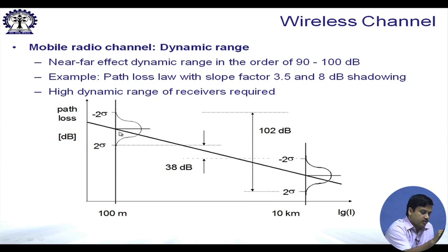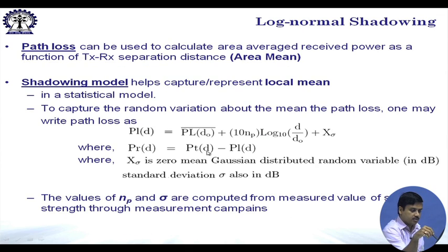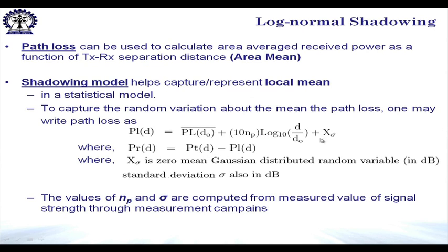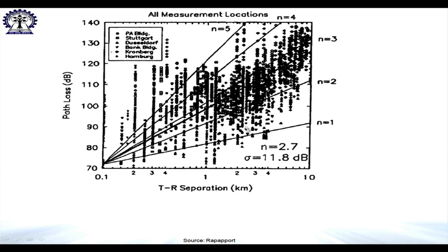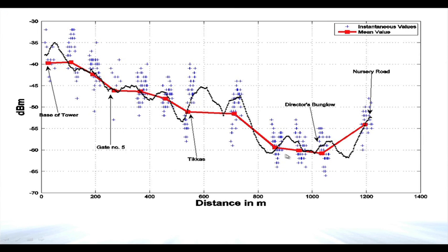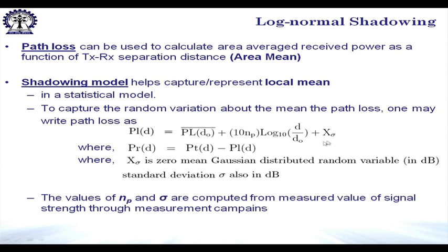That means, when you are close to the base station, you would get fluctuations beyond this, where the maximum received signal strength would go even beyond that predicted by the average because of the random fluctuation. If you see this model, there is random fluctuation. To support this, if we look at this data, the signal strength can actually go above, meaning it did not decrease monotonically. If this is the average slope as pointed by the cursor, it could go below the average. So, there is fluctuation above and below the average, and this is zero mean.